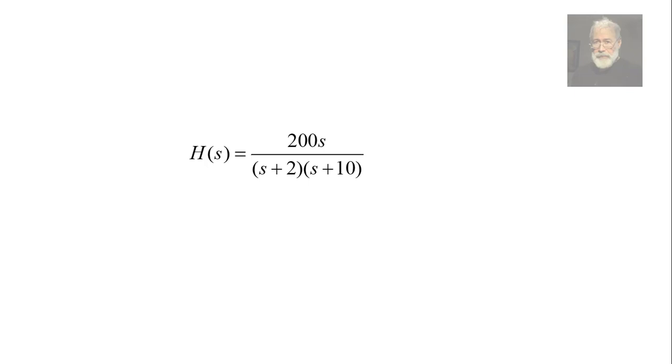The constant, being a real number and all, will contribute to the phase with 0 degrees. The 0 and 0, once you replace s by j omega, becomes an imaginary number, and it's contributing with 90 degrees for every frequency. The pole at 2 and the pole at 10, each one will contribute with 2 corners, one decade before the pole and the other 1 decade after.